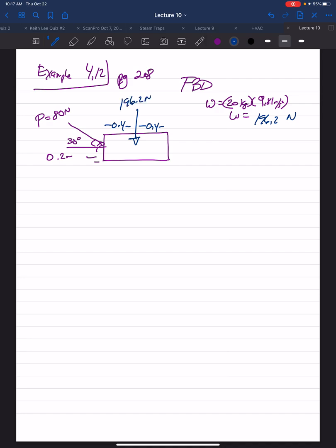All right. We have a frictional force. The pushing force is pushing it to the right, so the frictional force is resisting movement, so it's opposite in direction to the force. We have a normal force, where we said the line of action to prevent tipping is somewhere off the line of action of the weight.